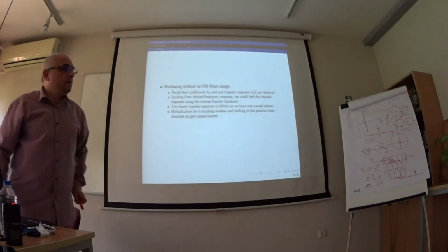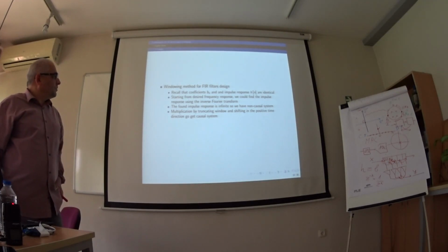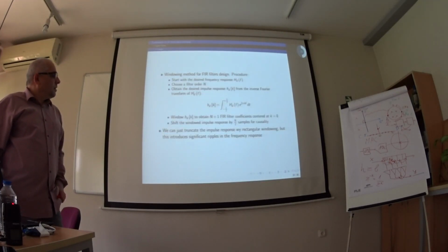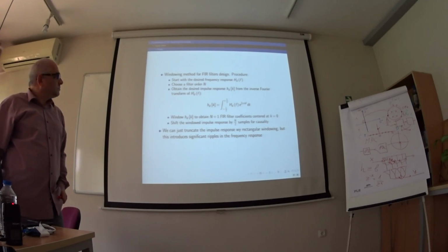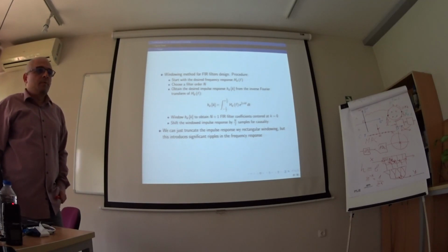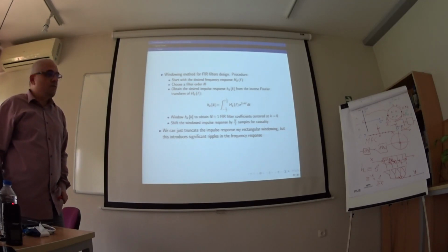How to design such FIR filters? We choose a magnitude response and we want to find the impulse response. We can apply inverse Fourier transform to find the impulse response, and the impulse response is our coefficients. But